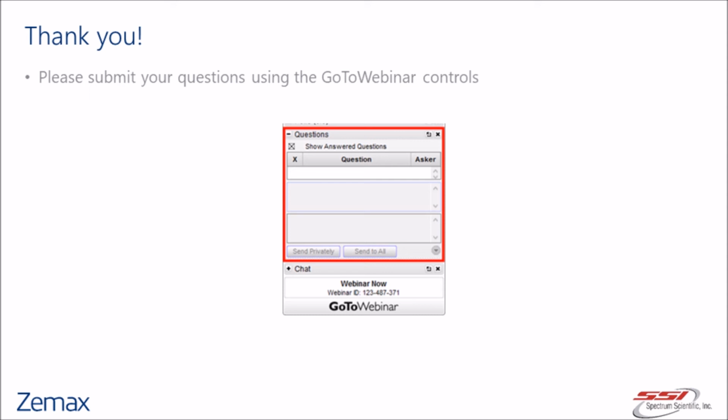Okay. The next question is for you too, Grant. How many replicants can be made from a master? The answer is thousands. We are in production right now with a single master. We always have a backup master, but we've been running the same master for over 10 years already, and we've produced thousands of parts from it. So the masters don't really wear out or degrade? Right, and just to make it clear, we'll take a submaster and step down away from the master to preserve the master, and you get many hundreds of takes off each submaster.